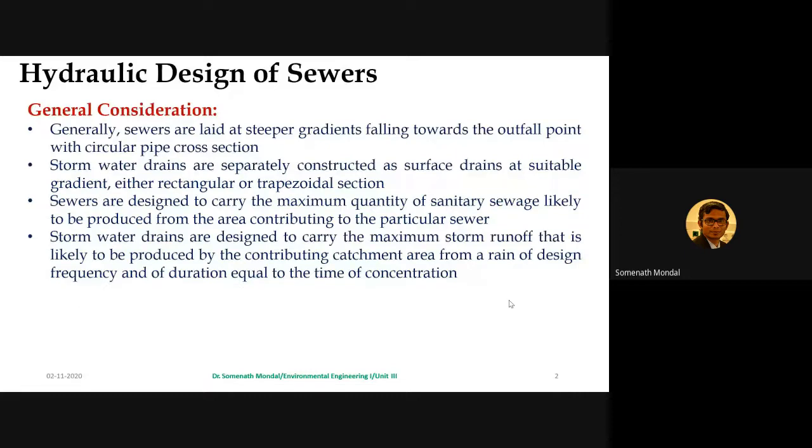Next, stormwater drains are designed to carry the maximum storm runoff that is likely to be produced by the contributing catchment area from a rain of design frequency and of duration equal to the time of concentration. That is why earlier we spent a lot of time determining the time of concentration, critical rainfall duration, those things, because ultimately you are going to measure the maximum storm runoff, and that is very important for designing the stormwater drains.